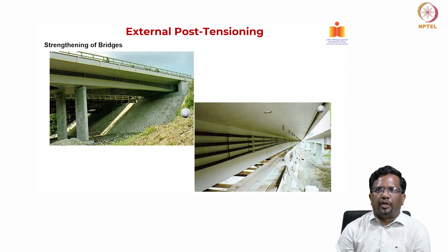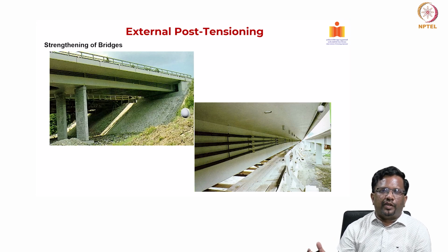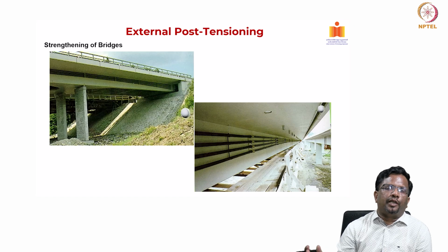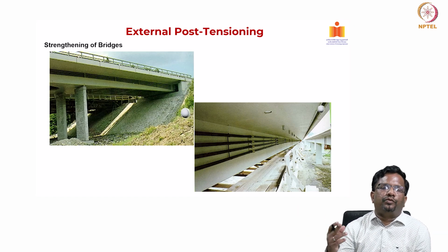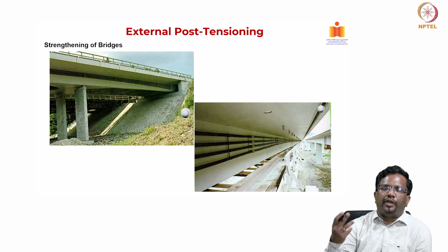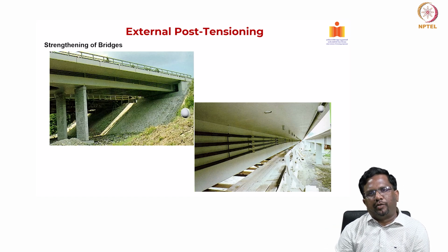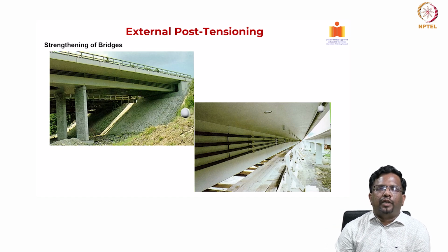And bridges, again, let us say if you are falling short of capacity or if it is having deflection issues, you can attach a cable from one end to another end and then you stretch it, and that again should follow the bending moment profile, then you create more capacity and recover the deflections. So, this is again external PT, very commonly used for structural strengthening of bridges.